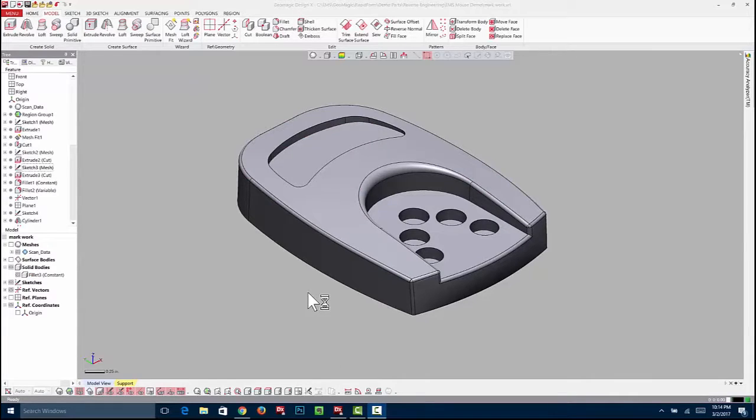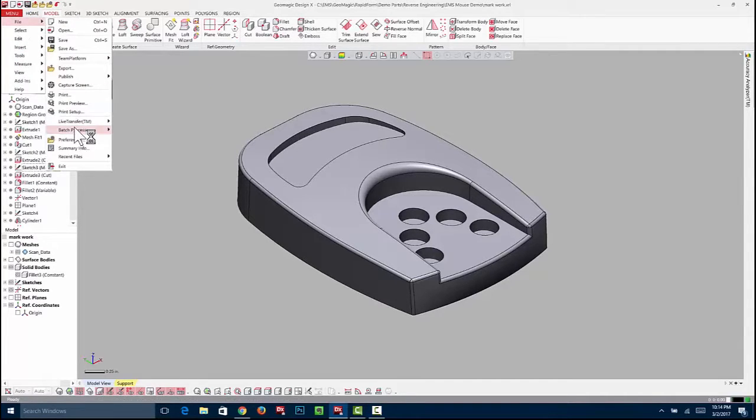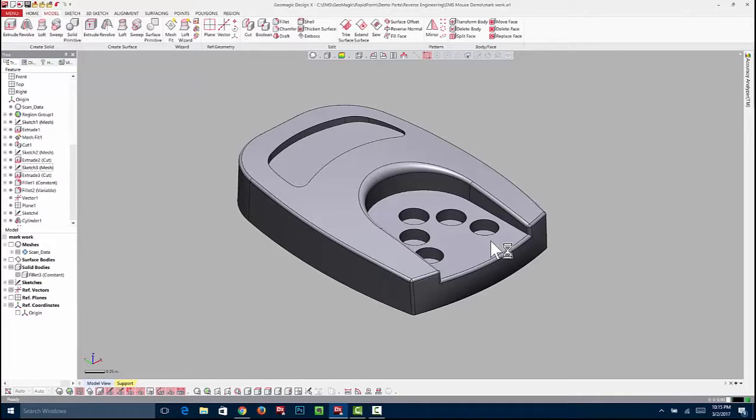The advantage of doing that is then you have a CAD model in your host CAD system with the history tree. Now, the live transfer is not perfect depending on what CAD system you're going to, anywhere from 50% with a product like Creo or Pro-E, all the way up to about 85-90% with Siemens, and SOLIDWORKS will go through, same with Solid Edge, because they all use the same Parasolid kernel. Inventor works pretty well, AutoCAD works pretty well. So that's another real advantage, is now you get a history tree model in your native CAD system that you can work with.